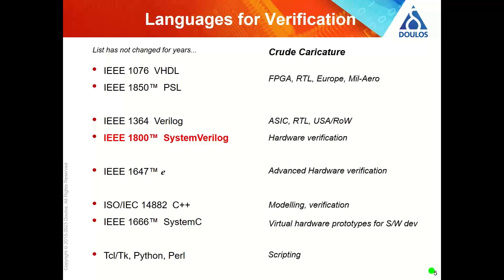But if you're creating virtual prototypes where you want to create a model where you're going to be running software on a mock-up of the actual hardware, then SystemC is really the leading technology in that field at the moment. Okay, so we could write test benches in SystemC. And again, you might have heard of SystemVerilog UVM. Well, there's even a SystemC implementation of UVM if you really want to go down that route.